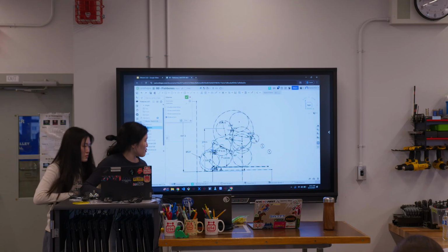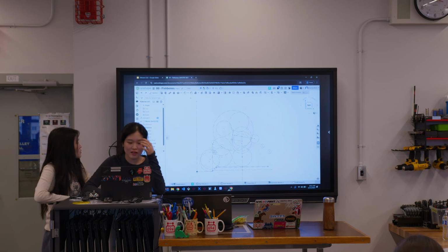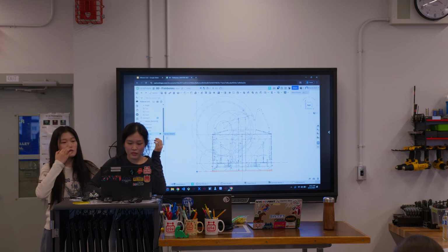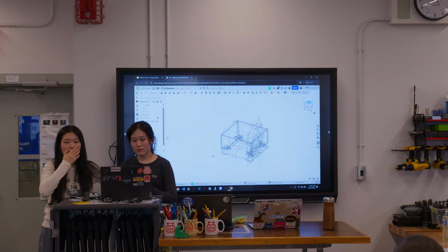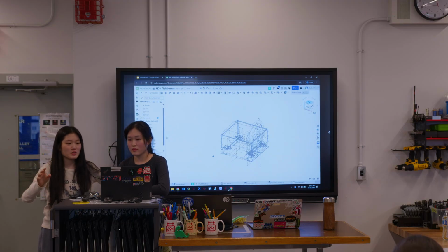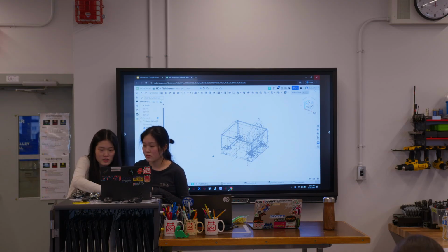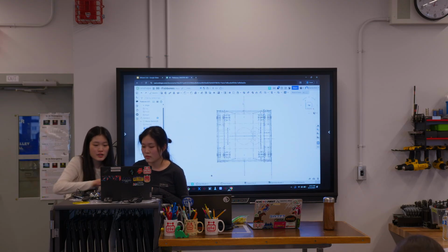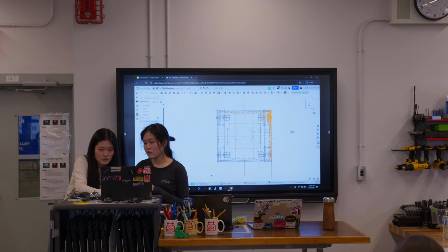So basically it's a shooting game. You have an intake and you have exit through the shooter. So these map out the ball path of where the ball will go. So when you guys are master sketching and you're confused on where to start, think about what viewpoint is the most important. Originally we started with the top view of the drivetrain, the top view this way. But then we realized everything is usually dependent on the side view because the side view shows how the ball travels.